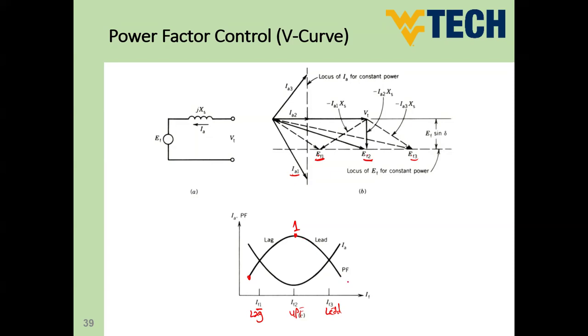The power factor of the motor, not the power factor of the connected loads in case of power factor compensation. So I don't care about the power factor of the motor now. I'm caring about the power factor type. Is it lagging or leading? I mean, the target is to improve the power factor of the overall system, not to improve the power factor of the synchronous motor itself. I just care to have leading power factor in order to get the maximum reactive power from my synchronous machine. So this curve, guys, is the power factor relation with the excitation.